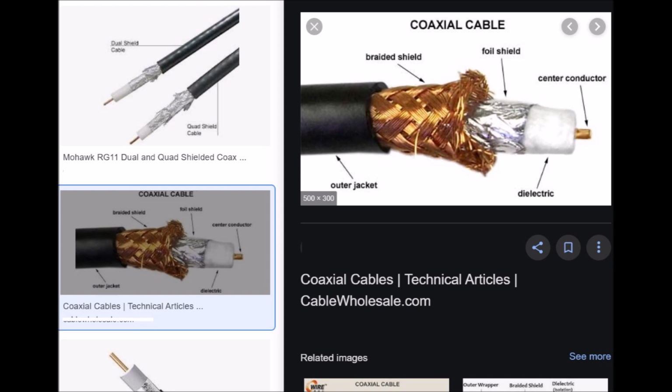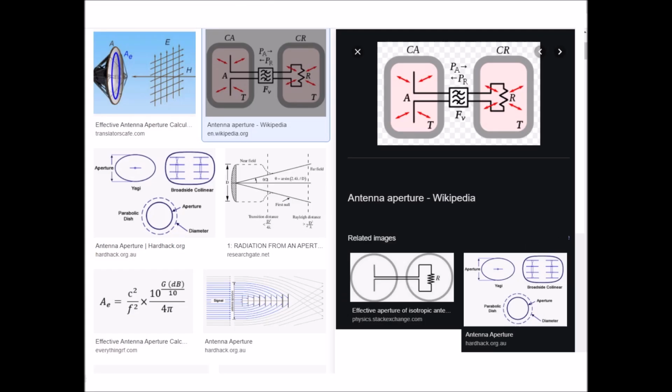An electromagnetic wave refractor in some aperture antennas is a component which, due to its shape and position, functions to selectively delay or advance portions of the electromagnetic wavefront passing through it.